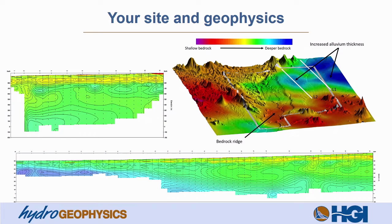This combination of geophysical surveys can image to depths far greater than the capabilities of other geophysical surveys. Impressively, the depth of investigation for AMT data is up to 1 to 2 kilometers, or 3,000 feet below the surface of the Earth. The deep exploration potential lends well to geothermal exploration, characterization of brine extent, deep structural investigations, and groundwater and mineral exploration.